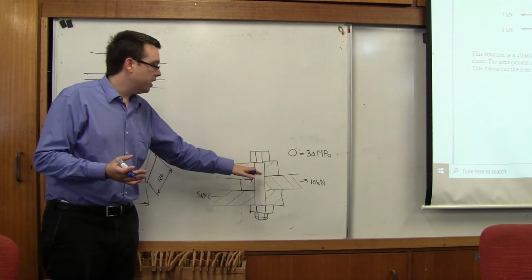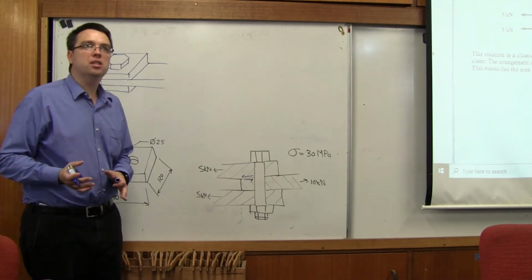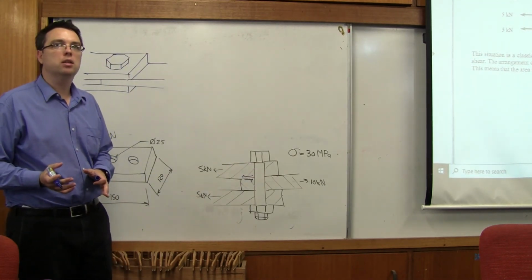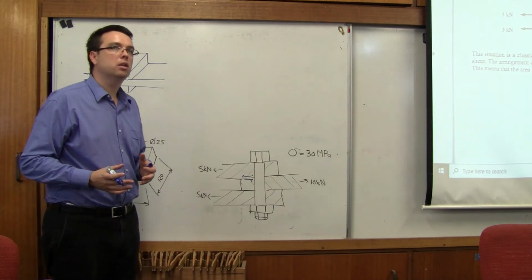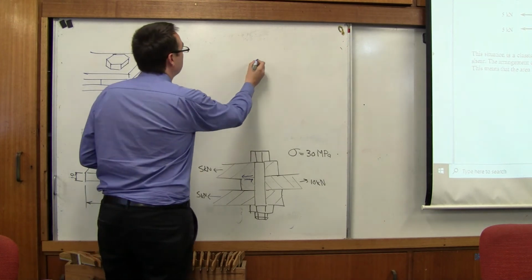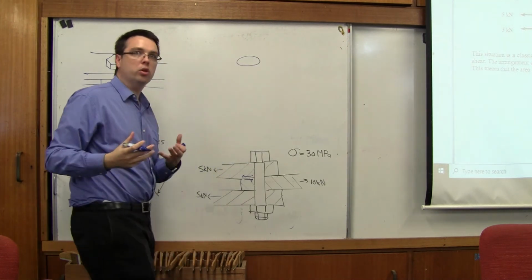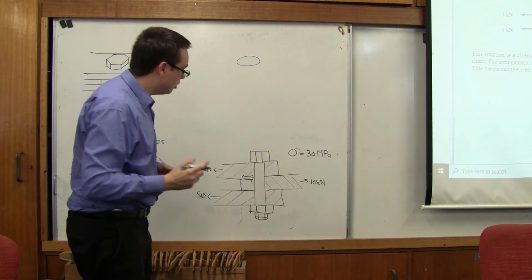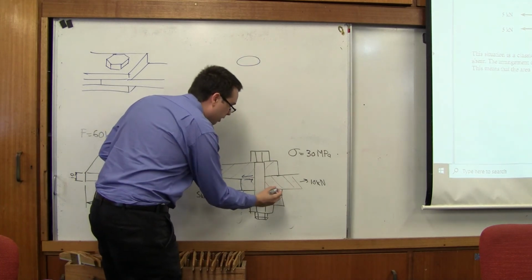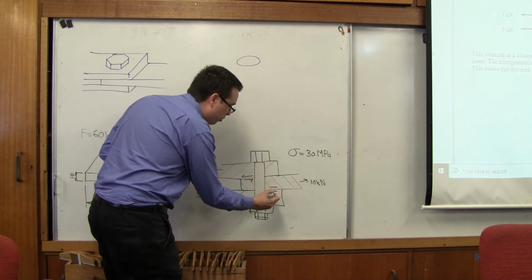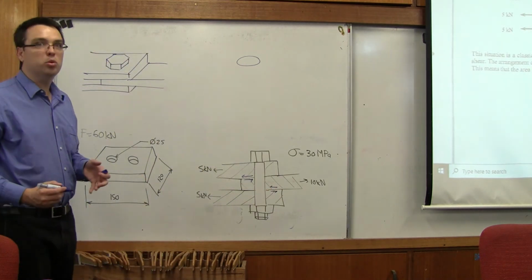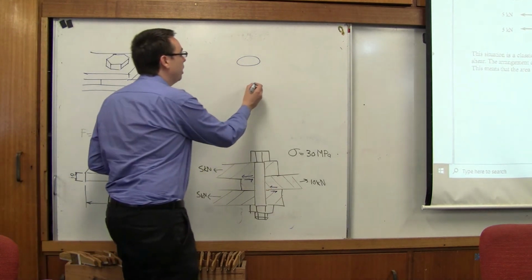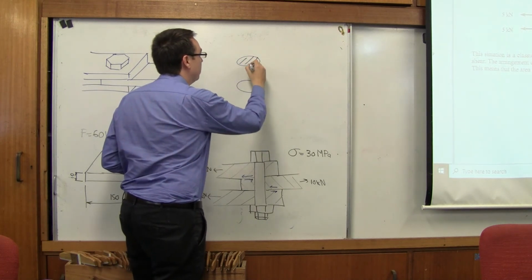Now, what is the area of material that is being slid past here? What kind of shape is it going to look like? Circular, right? It's going to be the circular section, the cross-sectional area of the bolt. What makes these questions interesting, though, is that if we have multiple pieces of steel, in this case we have double shear. That means we have 2 circles that we're calculating.